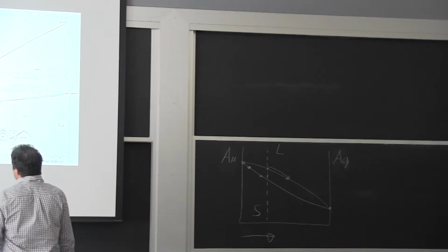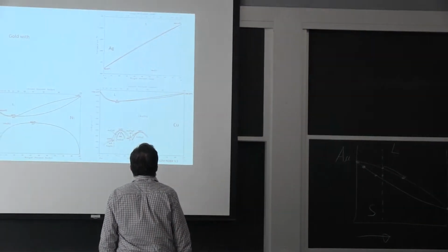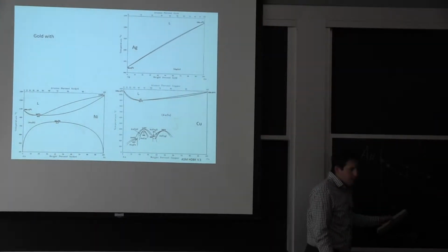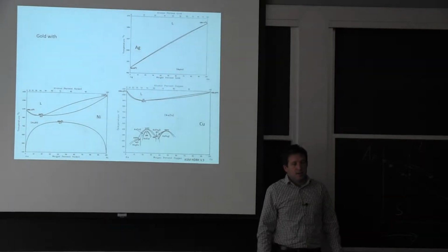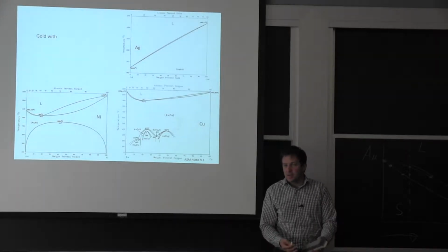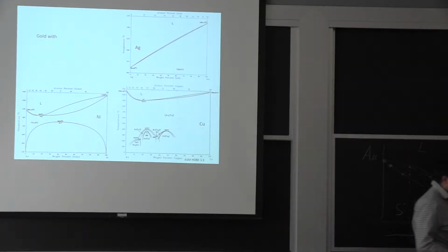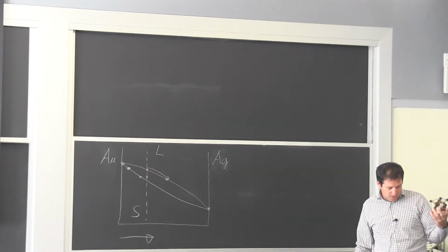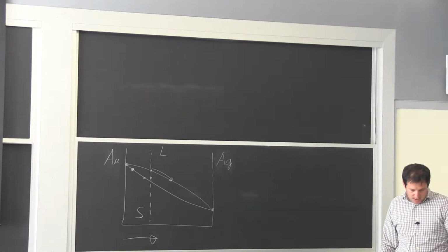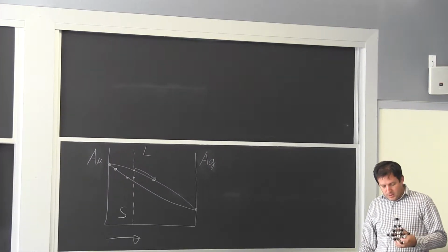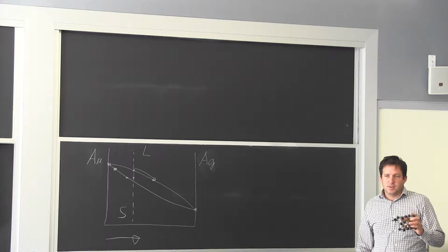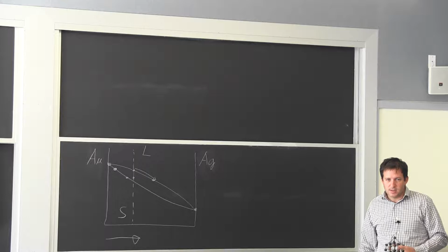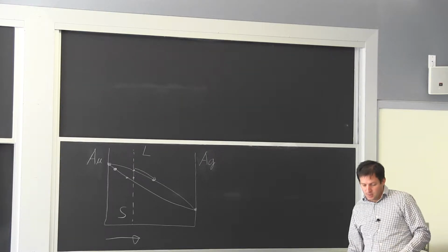There are not that many alloy combinations that you can put in any proportion. Here in the solid, it's going to be only one phase. They essentially have to be the same phase to begin with. So if we're talking about the face-centered cubic, the black atoms on this one, which is the case for gold and copper, it's one of the requirements. Then the next one is just about the same lattice size, atoms that are somewhat similar in size as well. So there are a lot of limitations to make that happen.